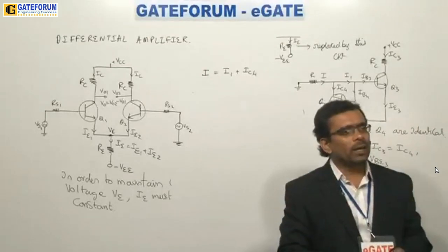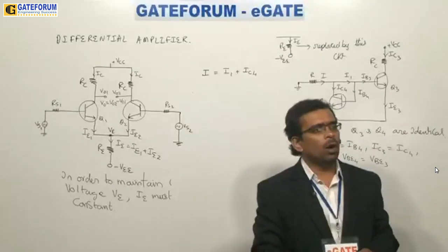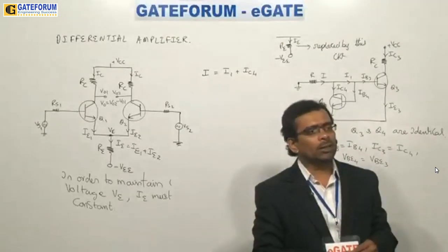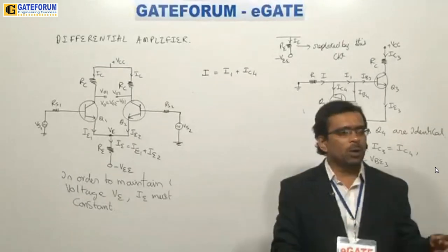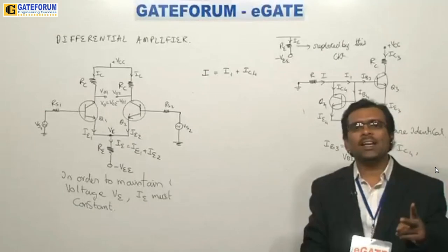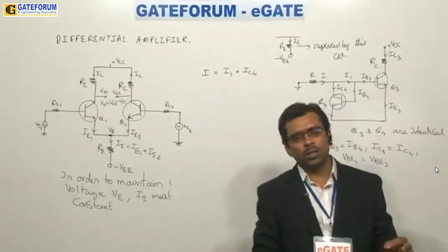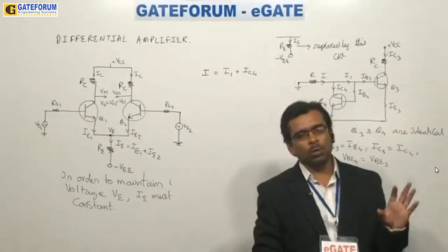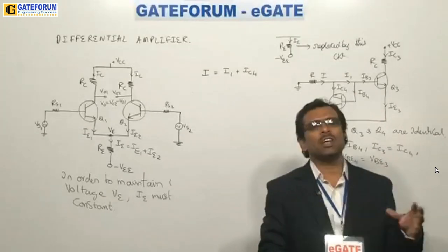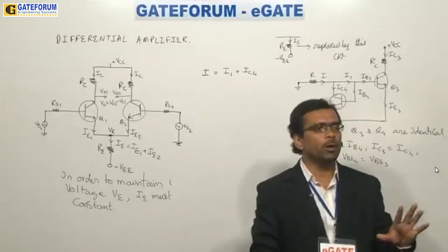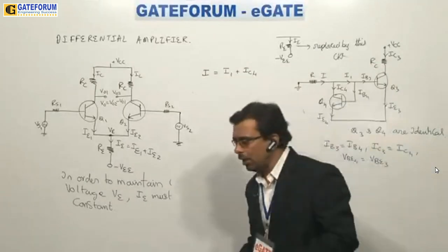Next, Saloni from Ahmedabad. In that collector based bias circuit, you took RB as 1.15. From this, we get one answer. But how can we decide the range of VC from this? It's very simple. VC can have only two options. Either it can become equal to VCC or it has to become 0 volts. Why? Because below 0.3 volts, the transistor will go to saturation. That is the point you need to remember. So you need to make a correction like this.